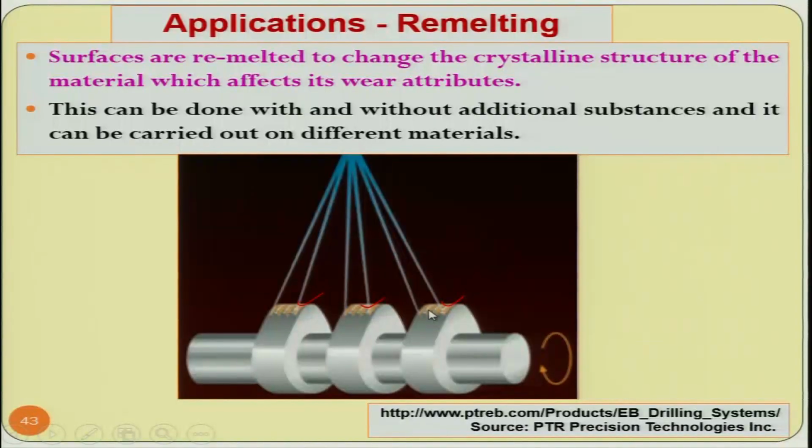You can heat it and then cool it at the desired rate. The cooling rate will govern what is going to be the final hardness of the material which you have melted. The material that you are melting may be the parent material of this particular part, or you can have external material being deposited here. For depositing the external material, you may have to create some kind of cavity where you can deposit this material. So all this will be decided by the designer.